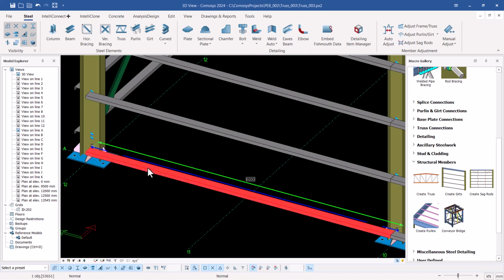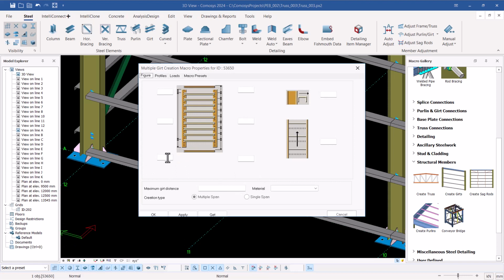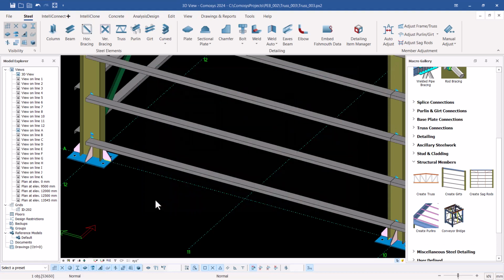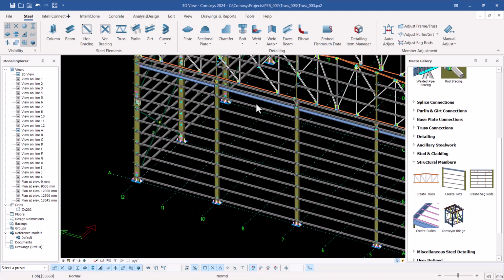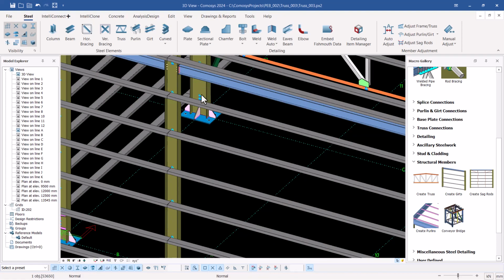So let me just select on that, press letter M and enter on my keyboard, and give some time to bring the editor dialog box so that we can edit everything to match our customized settings. So let me just key in a meter there, and on top here I key in 400, and I click apply and give it an offset. And if I zoom out, I'll be able to have these in place.